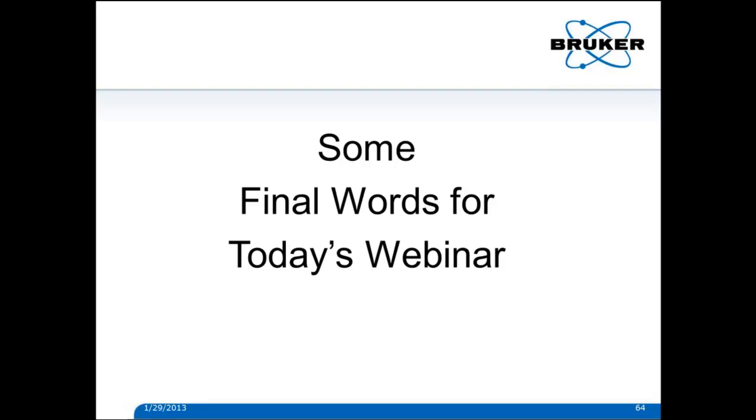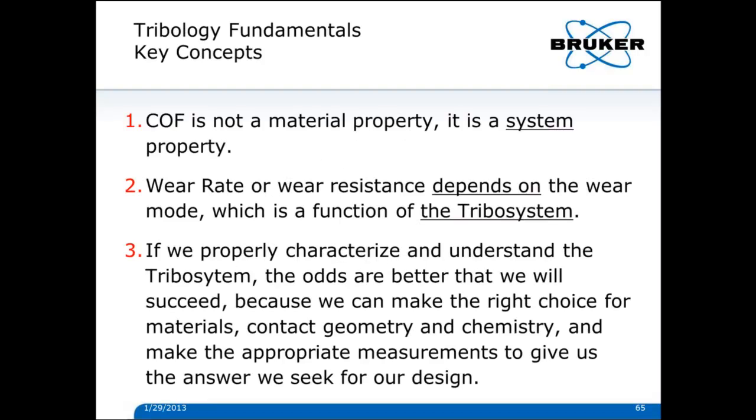So a few final words. I think we're on schedule here, so we can handle some questions for today's seminar. Key concepts I'd like to leave you with is that coefficient of friction is not a material property, it's a system property. We need to really simulate the system if we want to get the coefficient of friction right.